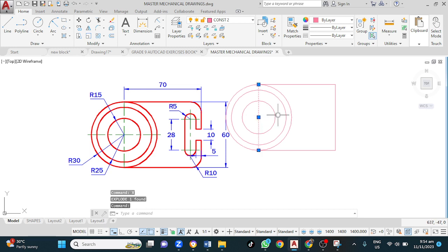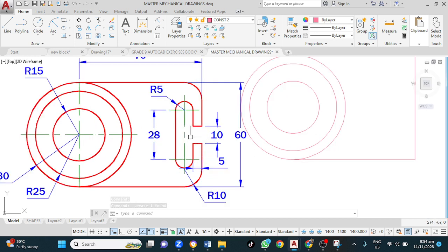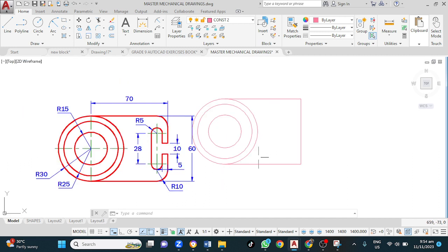I then left click on this and press the delete button. That's gone. Now to this section here, this can be done using about 6 different methods. But let me say the quickest one here would be to draw a line. This is 5 plus the radius is 5 to get the center mark. It's important to establish your centers first. Very important. So for that, I go for line.